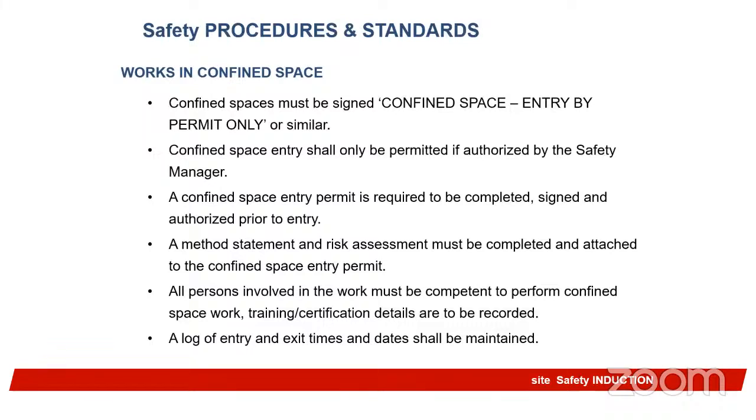There should be procedures for emergency response. There should be established procedures on the time that someone working in a confined space should use. Every 5 minutes, we bring one out, we put another person in, you rotate it like that. Then you should communicate all these things to the workers and make sure that there is a supervisor there. There should be a constant way of communication. Sometimes when we attach a rope to someone who is working in the confined space, what we do sometimes is that we shake the rope. We might have communicated with the person before going down.